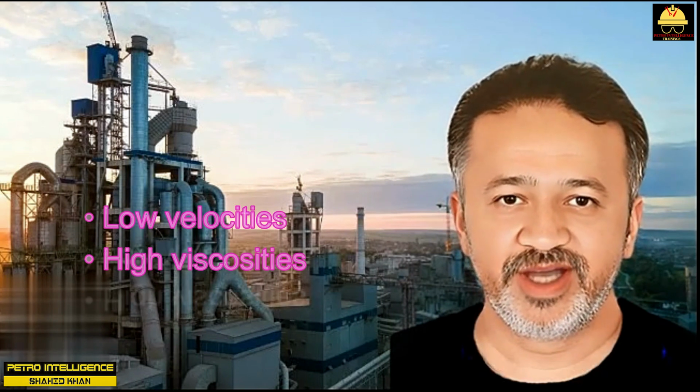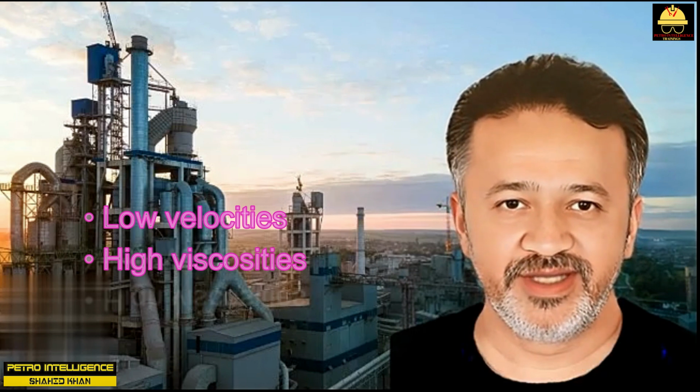Laminar flow is caused by two factors: low velocities and high viscosities. A low velocity for liquids is 2 or less than 3 feet per second. Velocities of greater than 10 or greater than 12 feet per second may cause erosion of metal surfaces and should be avoided. A low viscosity is 2 or 3 centipoise or centistokes. Tap water has a viscosity of about 1 centipoise. A viscosity of approximately 50 centipoise is quite high. Warm maple syrup has this sort of viscosity.